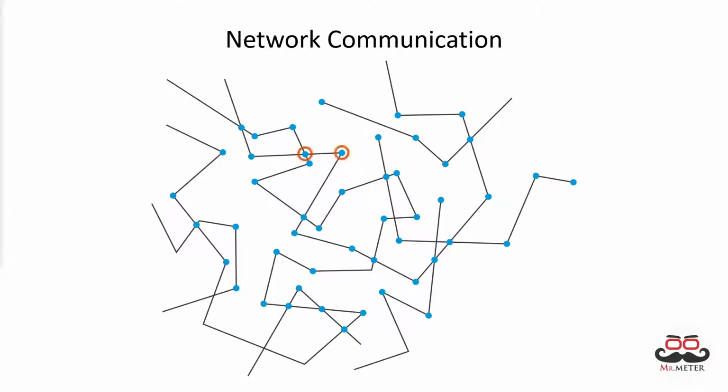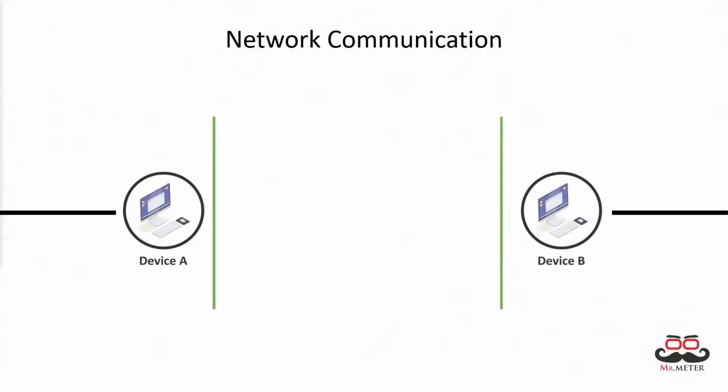When device A wants to connect and transfer data to device B, they first need to initiate and establish a communication or a virtual circuit and then transfer data. Starting a connection in HDLC protocol first happens by creating the first initiation packet called the SNRM packet. This is a typical connection initiation form in metering networks.